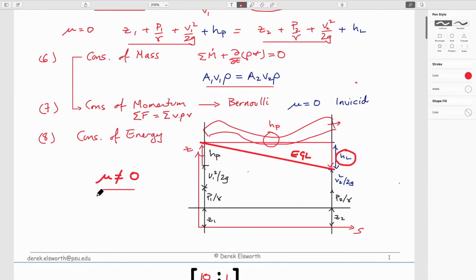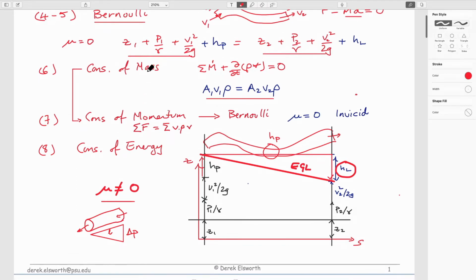And the mere observation that you do have frictional losses is that if you measure pressures between upstream and downstream, so if you measure a pressure differential, if you apply pressure upstream and you have a length of pipe as you're flowing water through it, the fact that you're losing pressure as you go from upstream to downstream, if you put that into Bernoulli, you'd find that if it's the same elevation, the elevations wouldn't change. If it's the same cross-sectional area, then by definition these two terms wouldn't change. And therefore the pressure upstream and downstream should be the same if there's no viscous losses.